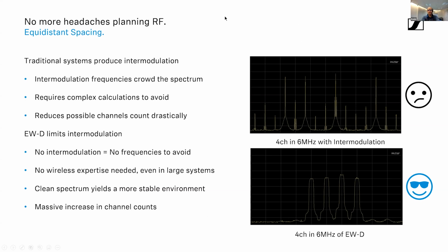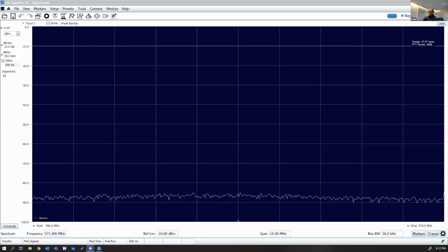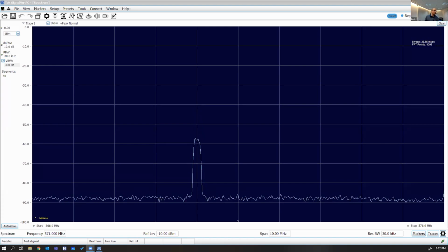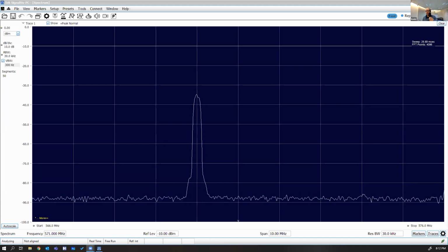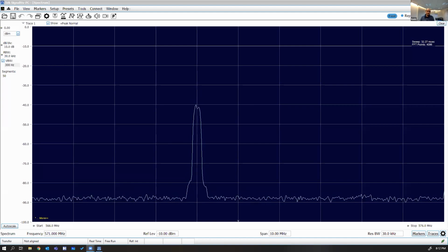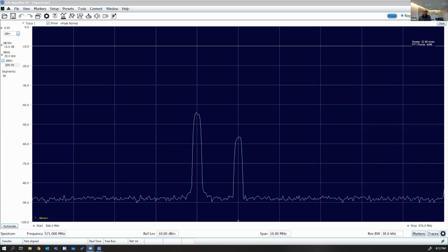Yes, let's do that. And here comes the scary part, because my entire professional life, I have been doing this, and I've always been doing frequency coordination and all these kinds of things. And this will be a thing of the past. I hope I'm not losing a job, but what you see now is basically one channel of EWD. It looks a little bit different than an analog carrier. It's a little bit wider. The reason for that is we're not looking only at the amplitude, we're looking at the modulation scheme and the noise coherence. So it uses a little bit more bandwidth.